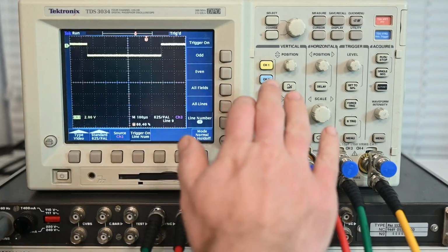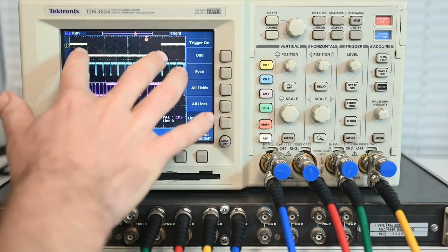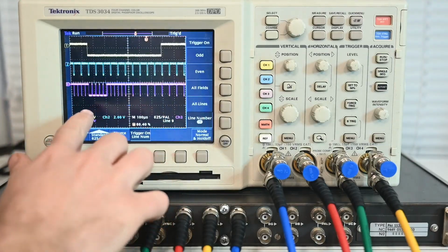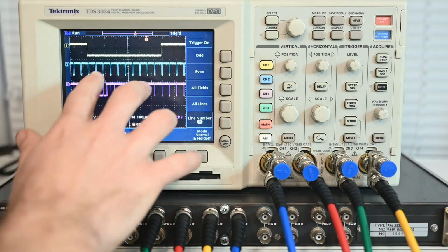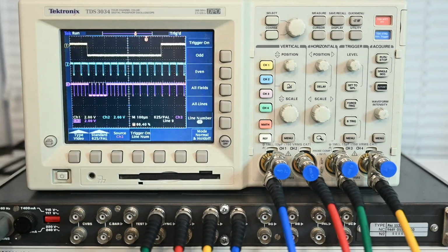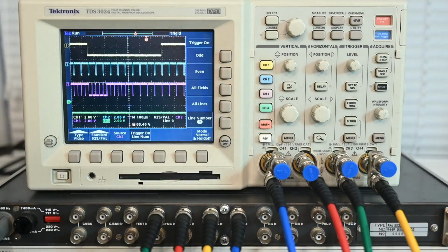So we're going to switch on channel number 2, which is the horizontal drive, and as you would expect, it's a pulse which occurs more frequently, once per line. Now next up we're going to switch on the mixed syncs, and as I said, this is a valid monochrome video signal of a black screen. Notice that we can see the components of the horizontal and vertical drive contained within it. The inversion of polarity here is the vertical drive, but note that the duration of it is different to the actual vertical drive signal.